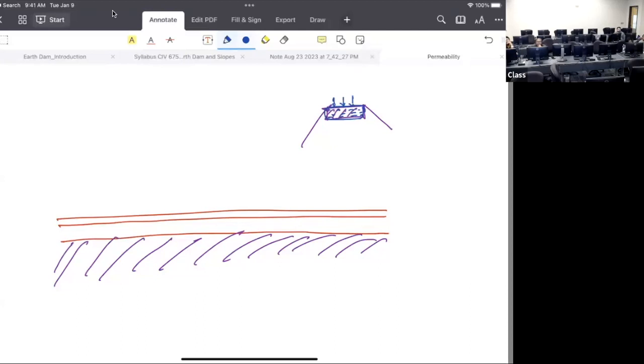There is clay, and water cannot pass through. So there will be some kind of punching, right? Now the materials will punch through the clay because your water is sitting here. So this area will be very, very wet, clay with very, very wet water in it. So what is the bearing capacity of those areas? Really low. Very low, right?